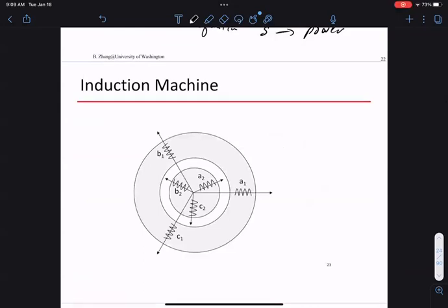So what does this look like in a circuit? From a circuit theory perspective, what does a rotating induction machine look like? It looks like six inductors rotating against each other. You have three inductors, which are the coils on the stator, and another three inductors, which are the coils on the rotor, rotating against each other. We care about how they are coupled together, which basically gives us a current and voltage being generated.